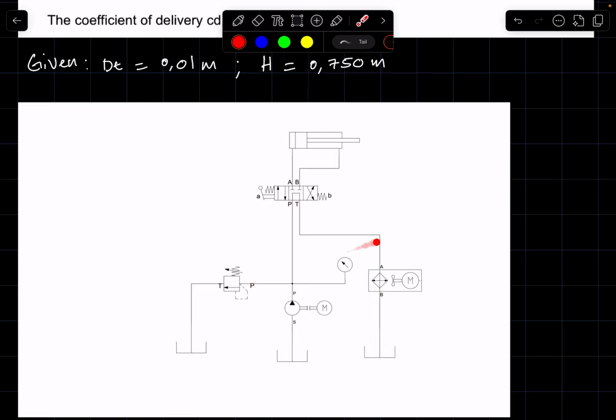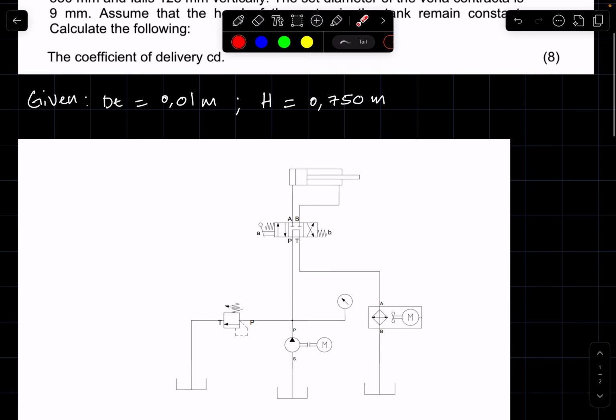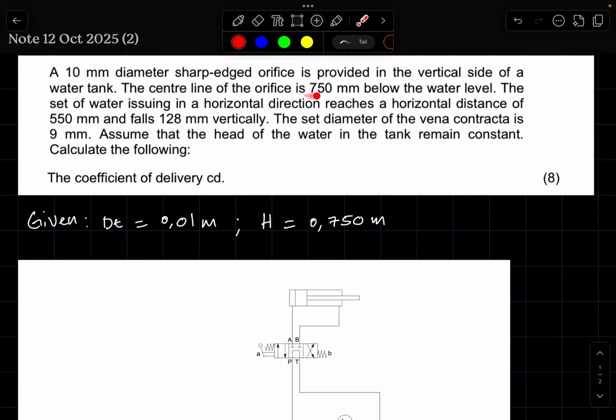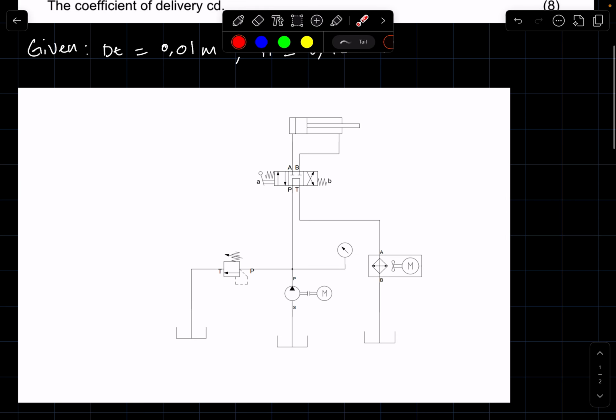Hence, this here, which I'll explain just now from the perspective of the schematic illustration of a flow through an orifice: the reason why the pressure head remains constant is because the fluid level in the reservoir remains constant, because the fluid being used is always drained back to the reservoir.